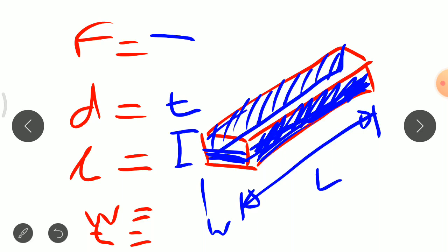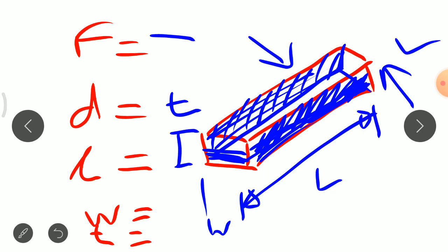So the stresses which are going to be produced in the key section, the resisting area is from this side or from this side, and we are going to take only one resisting area, so we will prefer this side resisting area, and the area becomes L into thickness or L into width section. Okay, we will see in details.